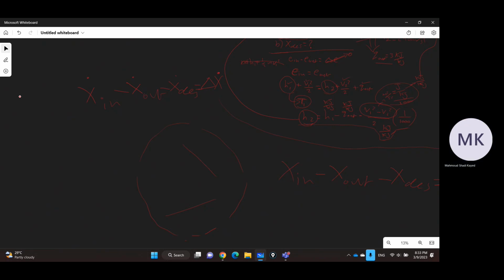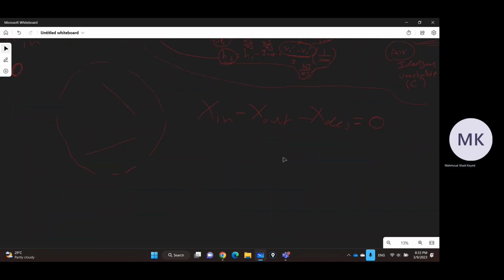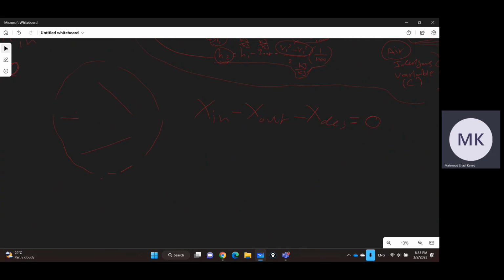It means that we are taking the change in the Exergy with respect to time, which is dX by dt, and we know that for steady devices no property is changing with time, which means that the change in the Exergy is 0 with respect to time. So now we have flow in, flow out, and we have a Q out.